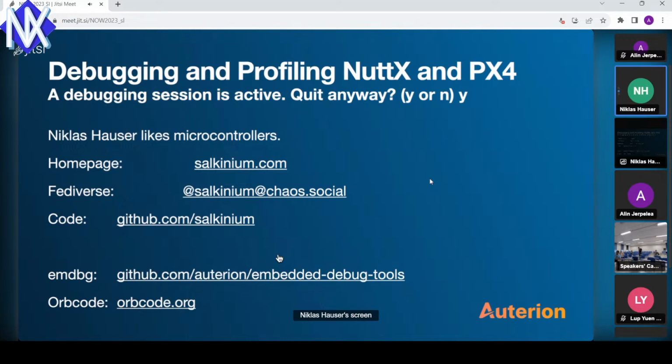So I'm not going to do any of that, mostly because we only use STM32. We use an F7 and an H7. Those are currently the 2 devices that are supported. But I did make sure that it works for NuttX, for some of the NuttX examples. At least it doesn't crash if you don't use the PX4 editions, because like the CPU timer stuff, that should work.